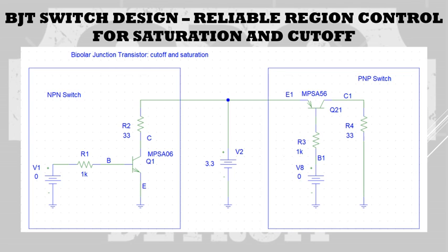The transistors that we have selected today for this example of how to turn on and turn off a bipolar junction transistor are the MMBTA56, the SOT23 package of what's shown here, and its brother from another mother, the MMBTA06. These parts, although in a SOT23 package, can handle a half amp of DC current through the collector and have a collector emitter breakdown voltage of 80 volts. These parts can be tied up to battery with no fear of breakdown from load dump.